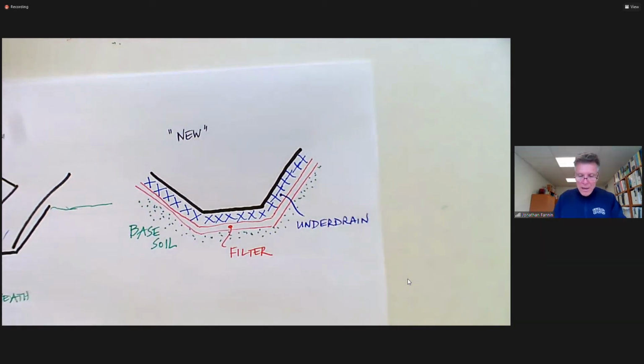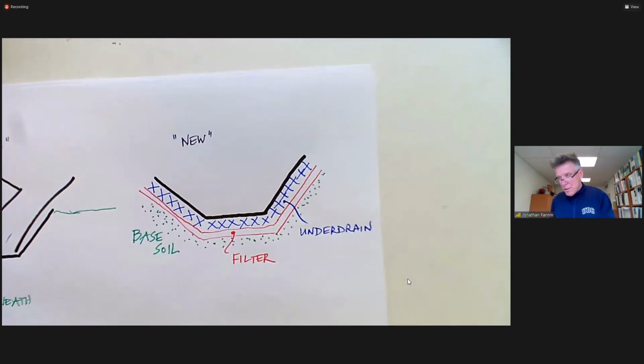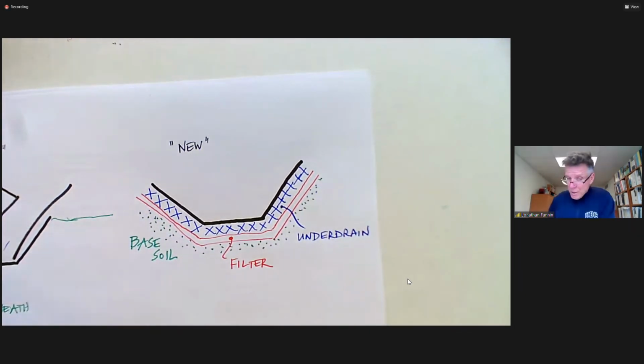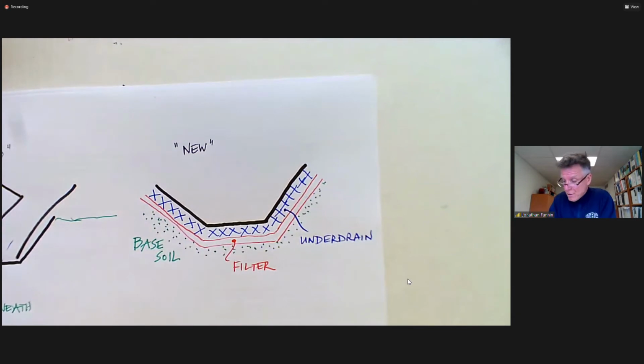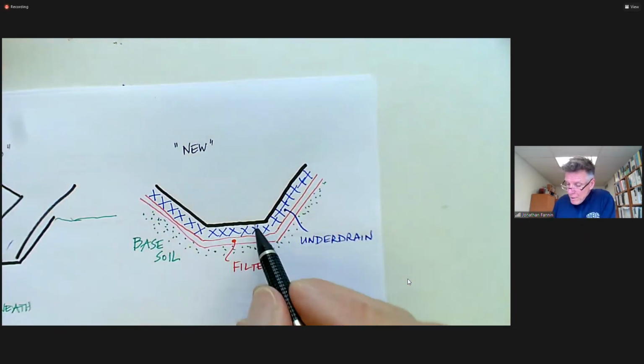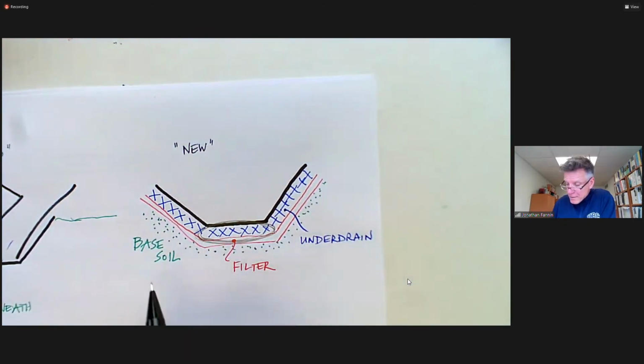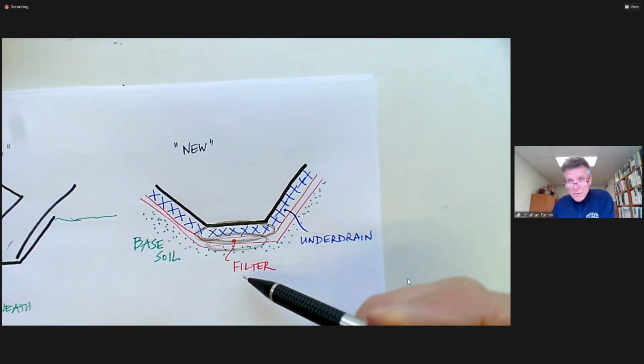And I take my hat off to the quality and foresight of the engineers at Hydro, and in particular, a colleague now retired at Hydro, or a friend at Hydro now retired, Steve Garner, who had the foresight to recognize, you know, when the contractor bids the work, they may be able to place the under drain with relative ease and compact it, and place the filter with relative ease and compact it, such that we can achieve base filter compatibility.